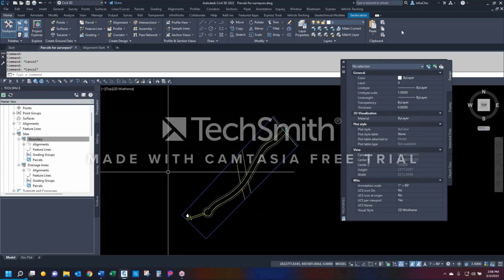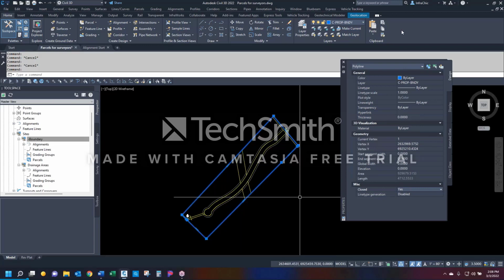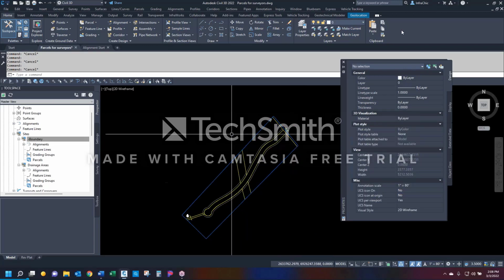Okay, so there are two ways to make a parcel. The first way: I've got my pins, I did the corner trace with my polylines, and I have an awesome-looking rectangular box. It may or may not be closed. In order to make a parcel work, it does have to be closed. If it's not closed, a parcel will not form. So I've got my awesome polyline.